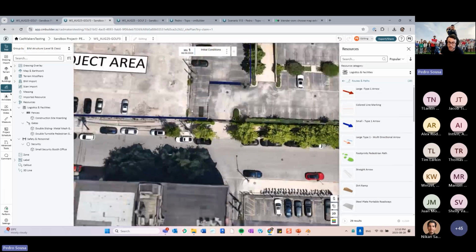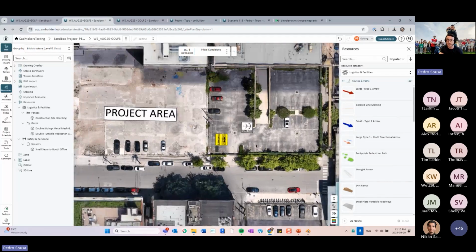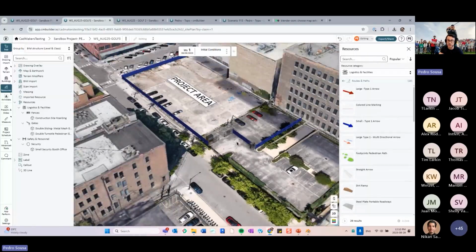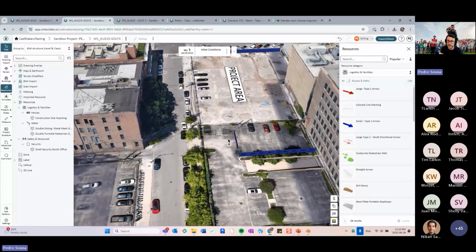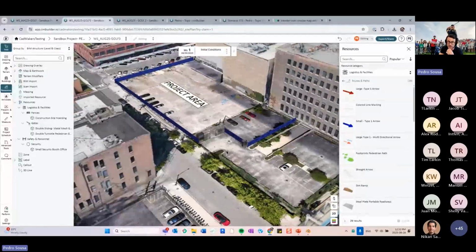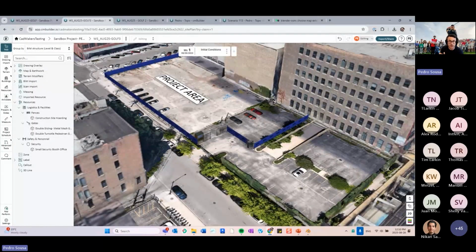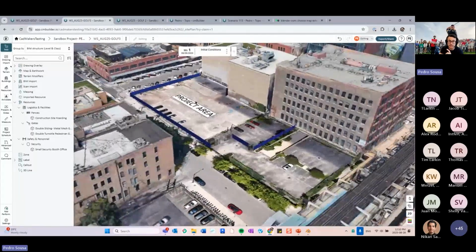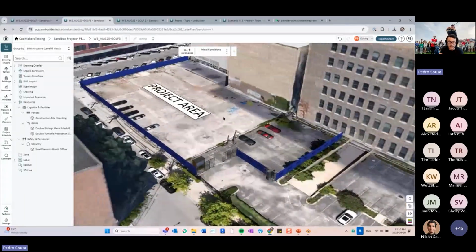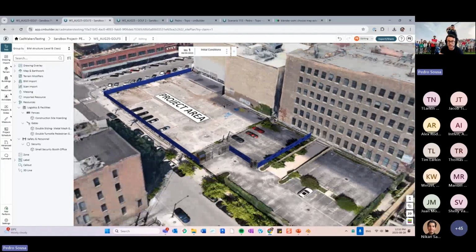One thing that is very important at this stage is also to represent where your emergency routes are going to be, like exits in case of an emergency, right? And one thing that I forgot to explain is that sometimes when you're doing your safety plan in cmBuilder, it might be interesting for you to create this in a duplicate scenario, so you can freely create your safety plan and adjust things, move things around, annotate, without having to worry about how this is going to look in your main scenario.